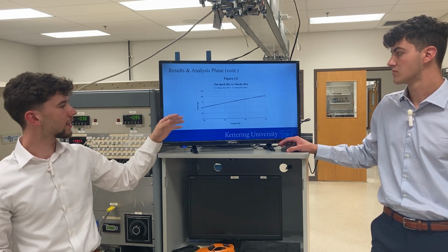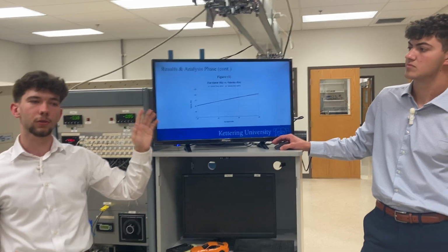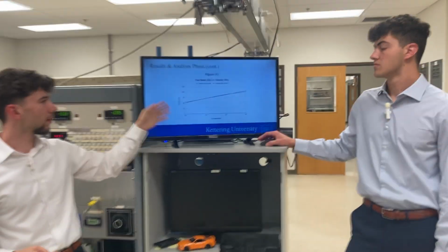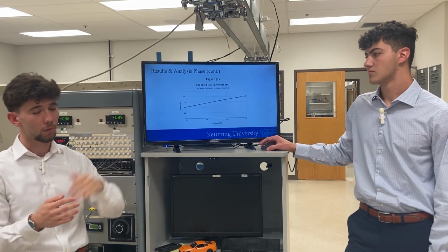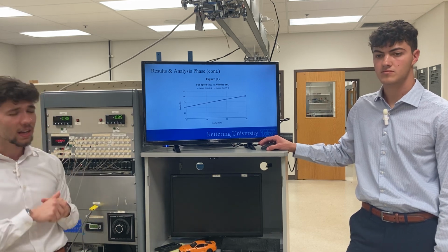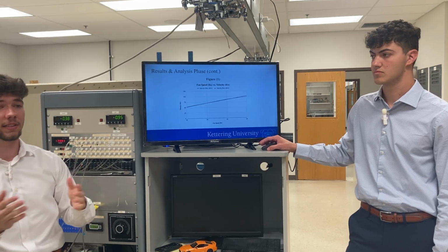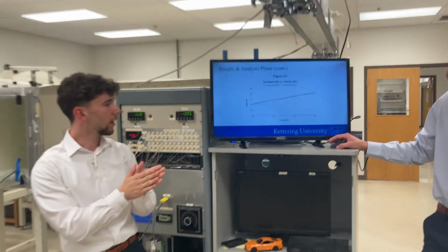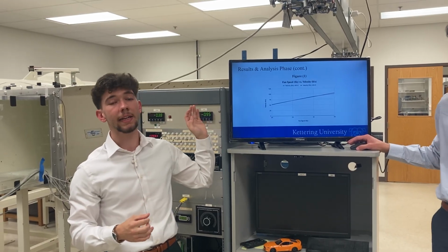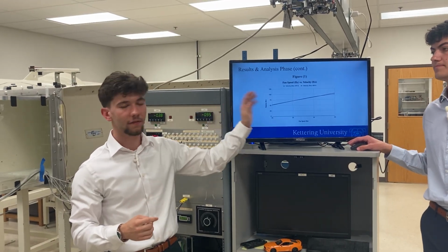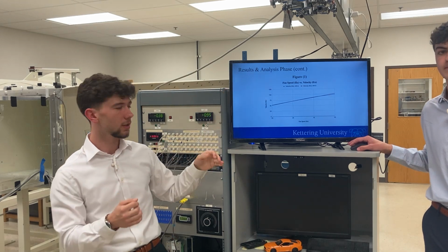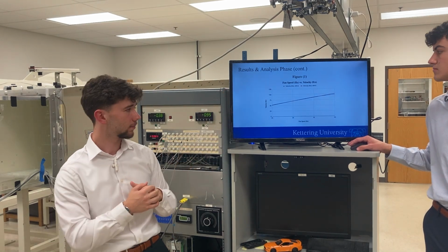What this is showing is that as the fan speed increased between trials, for both foils, the velocity increased almost directly proportionally, meaning that as we increase the fan speed, the velocity is going to increase by a similar metric. What this allows us to do is to plot each of our other key variables over the fan speed, and then we can make conclusions about how that changes with velocity as well.